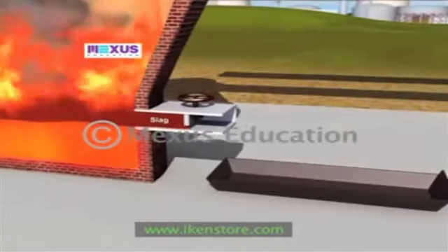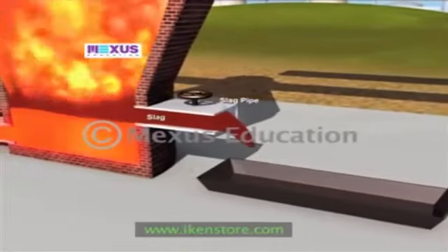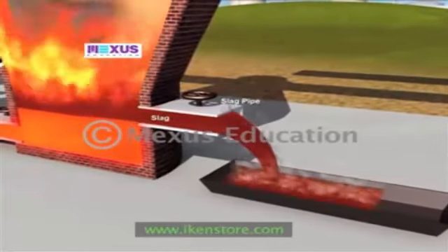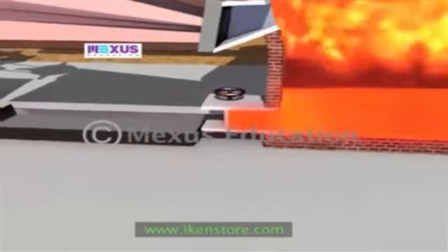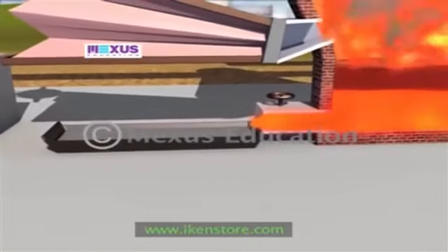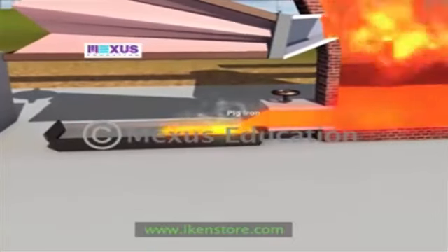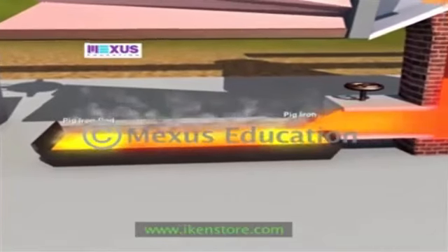The slag is drained through a pipe in the upper portion of the crucible, which is called the slag pipe. The iron is tapped from below and is run into sand molds to harden. The product is known as pig iron or cast iron, and the place where it is hardened is referred to as pig iron bed.